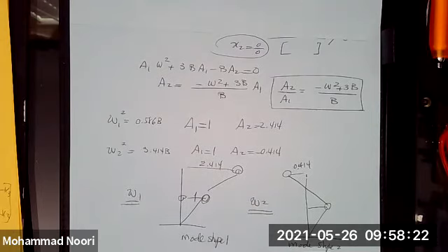But for the time being, all we can do when you're given a 2 degree or a multi-degree of freedom system is find the natural frequencies corresponding to each degree of freedom and the qualitative shape of deformation corresponding to that frequency, which we call mode shapes.